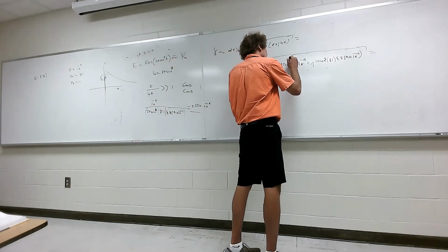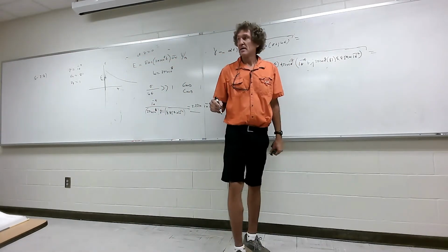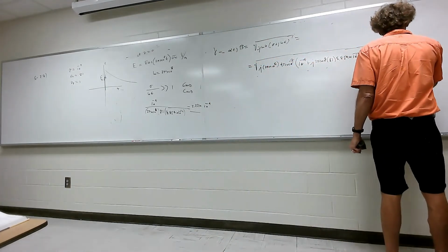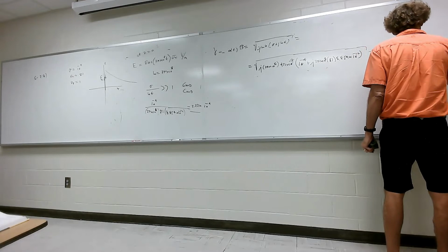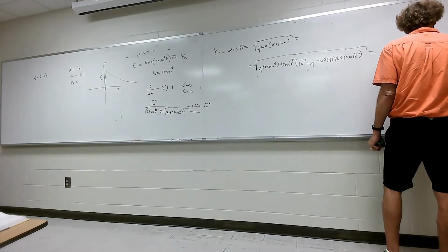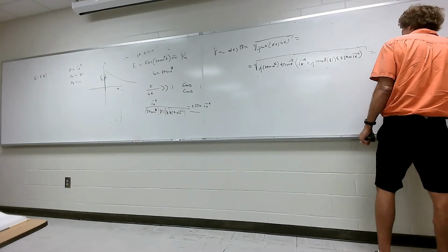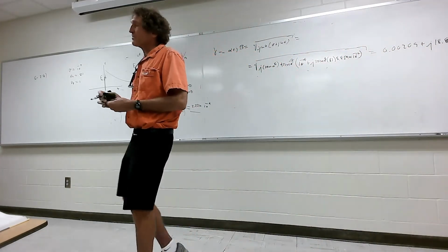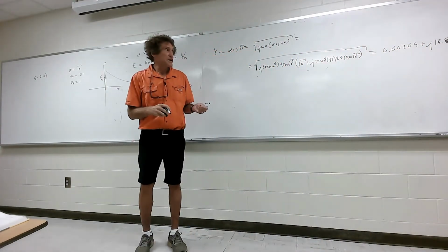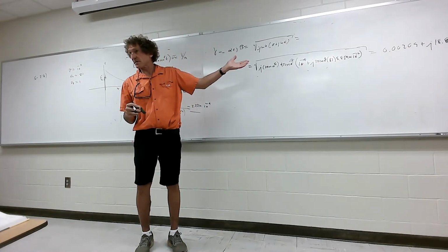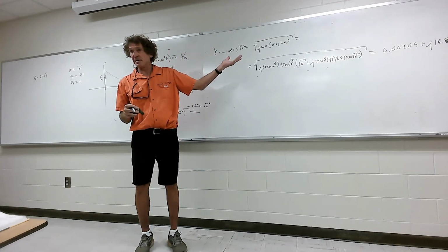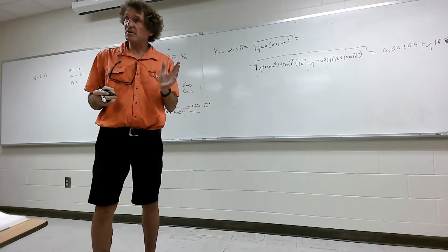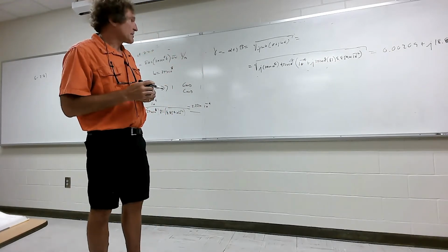There's a long story behind this, but I got 0.00209 plus 18.86 j. Anybody else? You got that? All right, I'm betting it's right, but you can see this is a very low loss dielectric. The alpha is just about negligible compared to beta. When the two are about the same, then you've got a pretty good conductor. All right, so we have this for gamma.